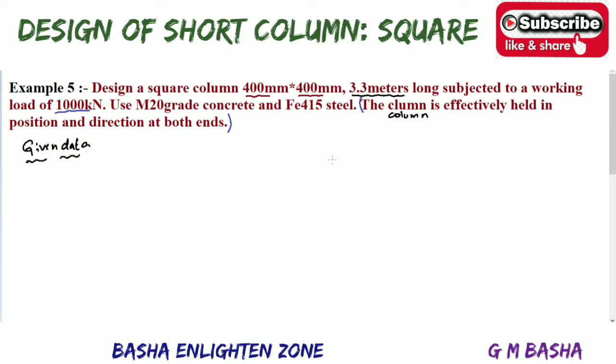In the previous problems, example 3 and example 4, they just mentioned that we have to design a square column. They gave the conditions, but they didn't mention any dimensions there. But they gave some data like axial load. Based on the data, we used a formula like Pu equal to 0.4 fck Ac plus 0.67 fy Asc.